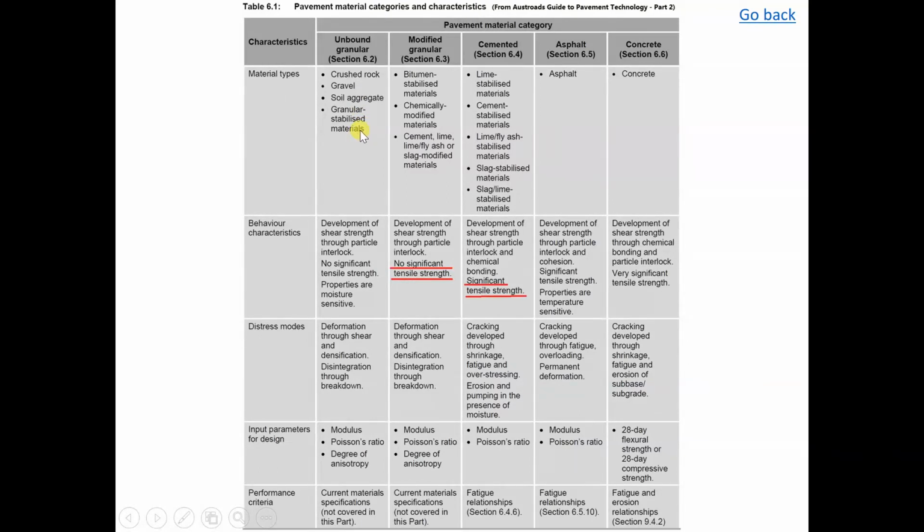That means that this is, for example, the ground, the subgrade. There could be some sort of granular stabilized layer. Rather than cemented, for example with lime, you could stabilize the material. You could stabilize the clay to provide volumetric stabilization, so there's no change in volume.